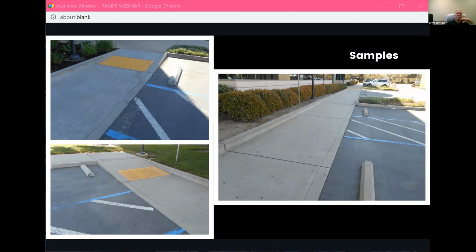The bottom landing and the top landing have to be as big as the ramp, and that's a minimum of 48 inches. I can't think of any code sections off the top of my head that require you to have a 6 foot wide ramp. It just requires you to have that width in the bottom landing.